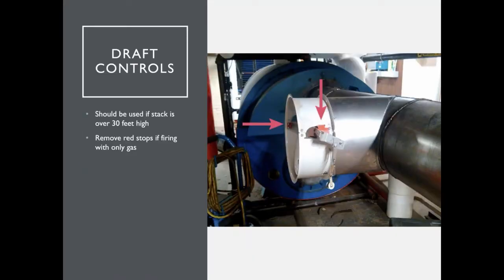Draft controls on a Category 1 boiler are used if the stack is over 30 feet high. One of the things we see all the time is they forget to take these red stops off. The red stops are only to be used if you're firing with oil. Now, there's some controversy regarding this, the idea being that if the flue gets plugged upstream or downstream closer to the chimney, this can open up and allow the flue gases to roll into the boiler room, which is a scary, scary thought.